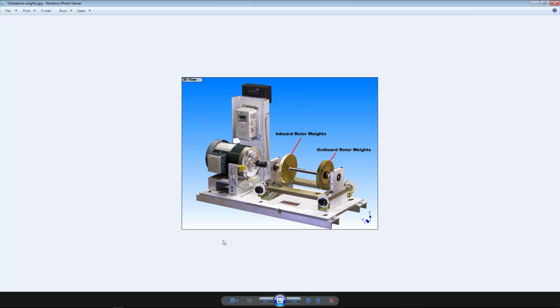Now the way we're going to diagnose this is using ODS data archived into a database. That's where we've identified these unbalanced cases, and then when ME-scope archives new data into the database, we're going to use something called FACTS, which is really a term that we created. It's called fault correlation tools, where we're going to correlate ODSs in the database with data that's been recently archived into the database.